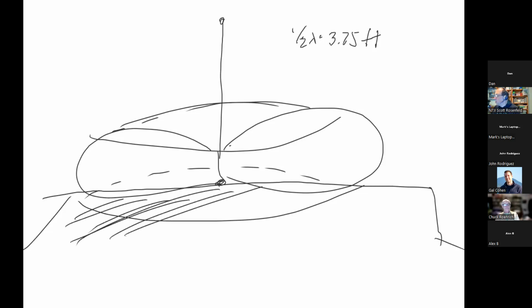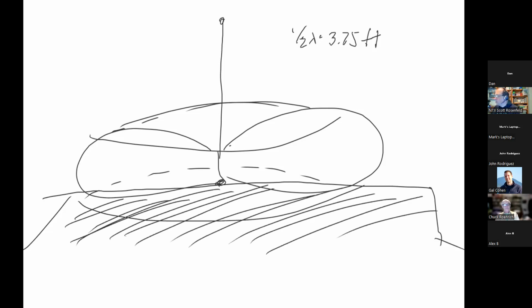And because the roof of the car is made of steel, which is a conductive material, what it ends up looking like is that the other half of this antenna is actually mirrored in the roof of the car. So this is a quarter wave, which is physical, and this is a quarter wave, which is imaginary. Now, I can show you what this looks like and make you believe this little parlor trick.